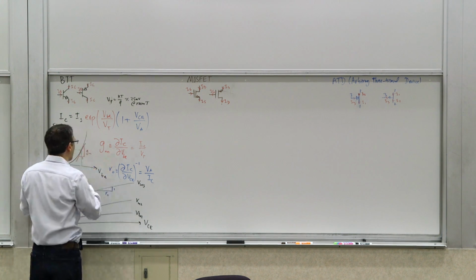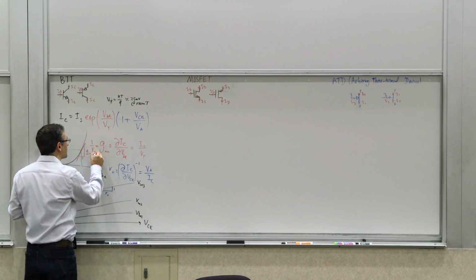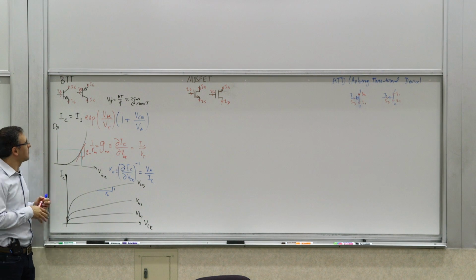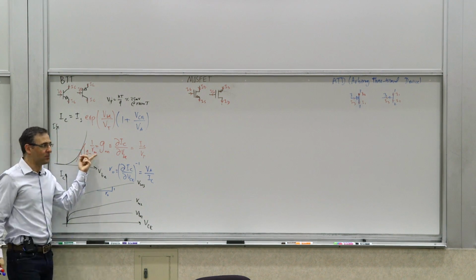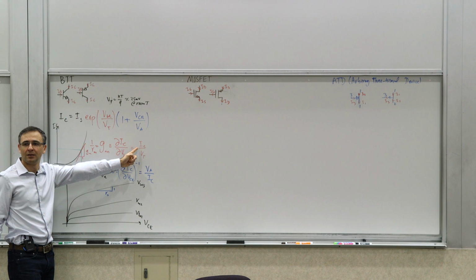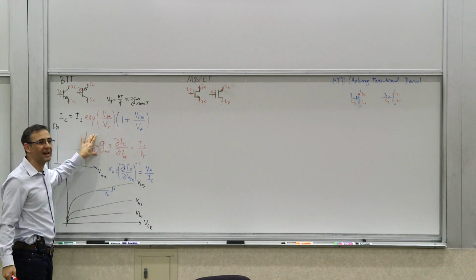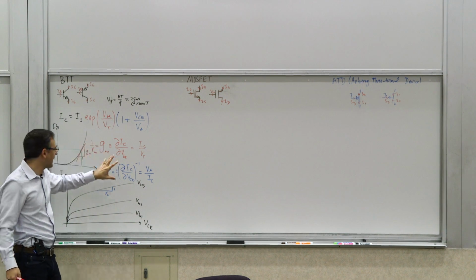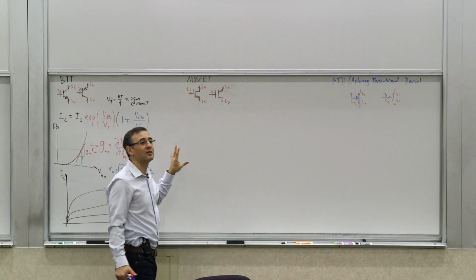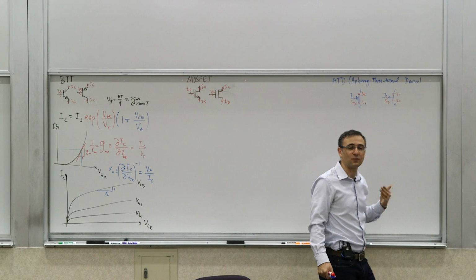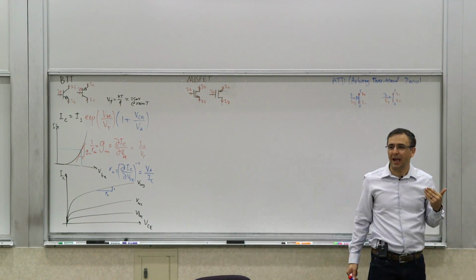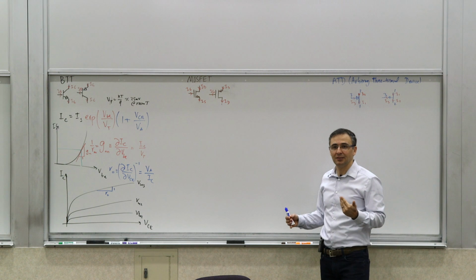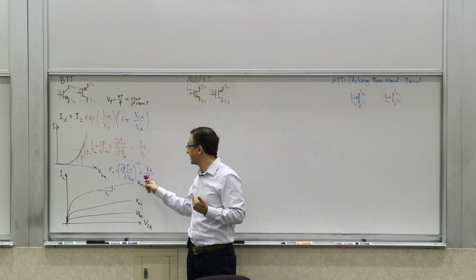RM, which is 1 over GM, by the way, and we use RM quite a lot from time to time, is going to be 25 ohms at 1 milliamp. So at 1 milliamp, you're talking about an RM of a few tens of ohms, and an RO in the tens to hundreds of kilo ohms. And you can see they both scale together, because they're both dependent on IC.